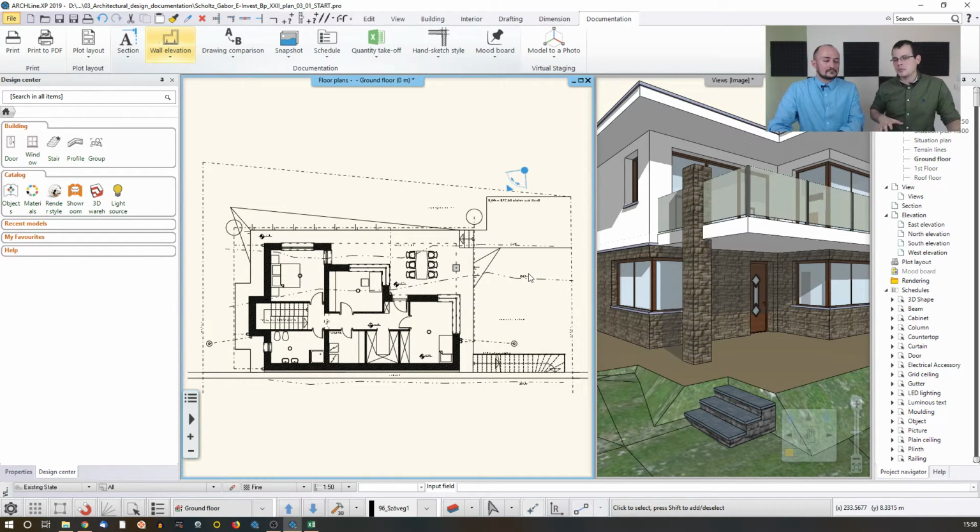One very important thing to point out, and that is something that we haven't done: whenever you are making an export, it's always good to export to subfolders. Like I did now. Exactly, because sometimes certain export formats, for instance OBJ, come with many additional files. So if you just export something to your desktop, then you might end up with hundreds of images and textures and things like that. So it's not what you want.